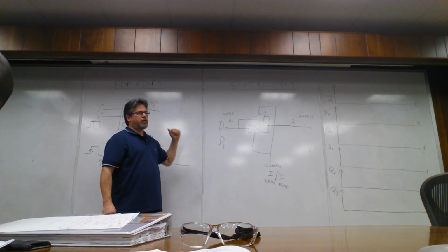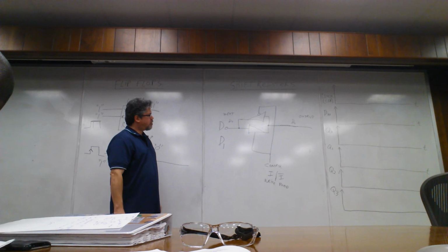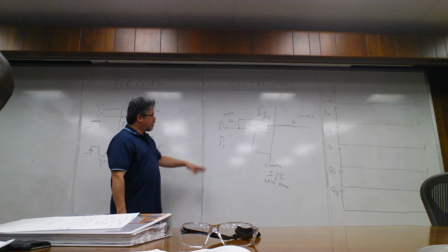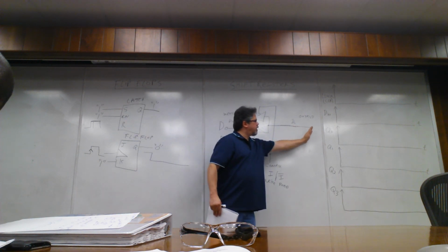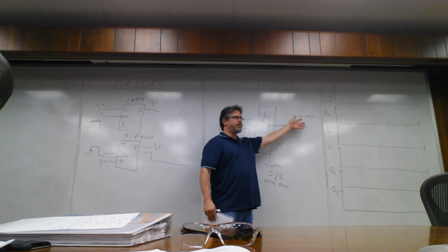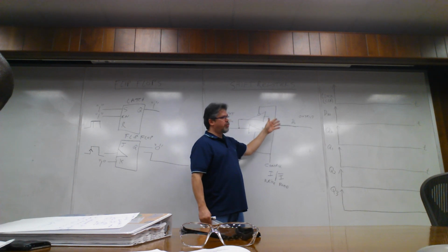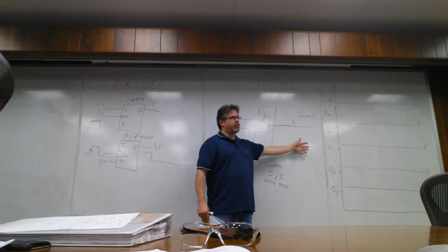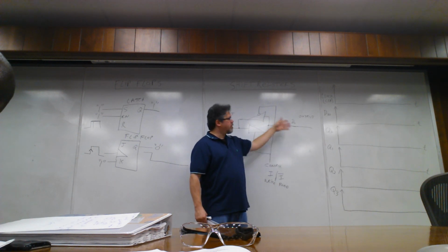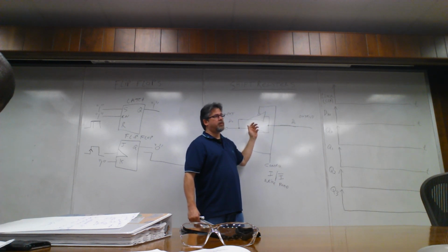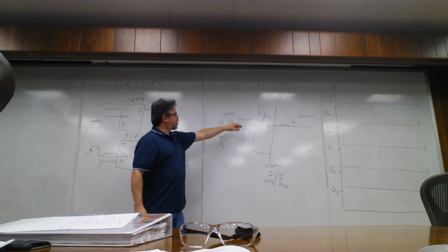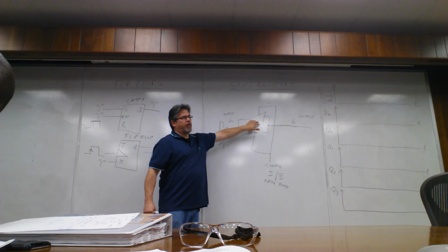So I'm taking in input, putting it on an output, pretty much according to another control. Right, because this peripheral device is just sitting here, and it has the data available. The data is there all the time. The micro doesn't want to be sending something out to another device while this thing is contending for that same bus. So it shuts that bus down with these called tri-state buffers.